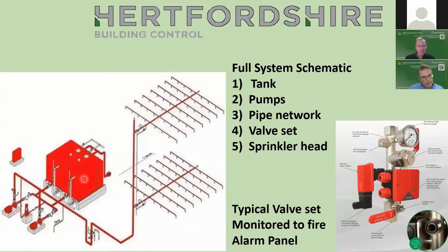But this is the tank, and this particular system appears to be the new Cat 4 system, where effectively that's 2 tanks, and you can see there's 2 water supplies coming from the same probably boosted cold water supply. So they discharge into 2 tanks. We've got 2 outlets into 2 separate pumps, and that will discharge the water into this distribution. We'll have a valve set there, a vertical discharge distribution pipe and horizontal distribution pipe.